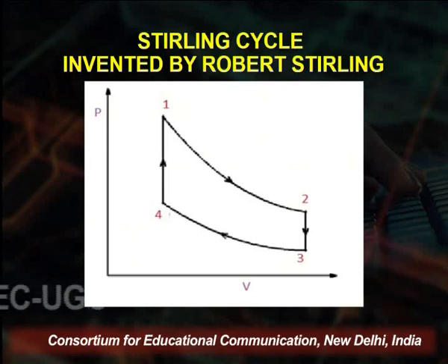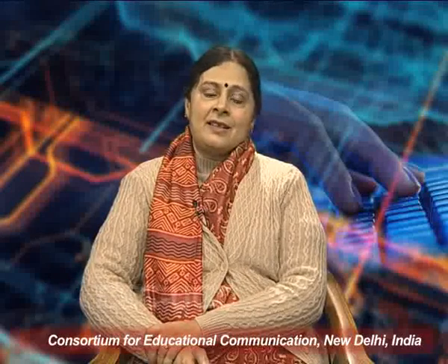You have 2 isochores, as you can see. This cycle is taking place between 2 isotherms and 2 isochores. It means 2 processes are occurring at constant temperatures and 2 processes are occurring at constant volume. Now please remember that wherever the process is occurring at constant volume, the work done is going to be 0, and wherever the process is taking place at constant temperature, the process is isothermal in nature and heat is going to be absorbed and rejected.